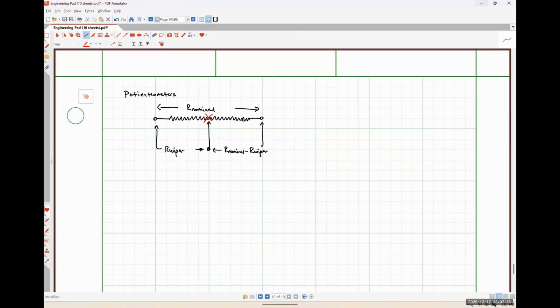Oh, actually, I guess one last thing. You can get potentiometers that have a linear taper, meaning that it's just a straight relationship. And then you can get ones with what are called an audio taper or a logarithmic taper. So audio taper and logarithmic taper are the same thing. They achieve that by literally just making the carbon trace get wider as you go across the wiper. So if you have a 500K pot with a linear taper, you'd be at 250 kilo ohms if you were exactly in the middle. With a logarithmic taper pot, you might be at like 100 ohms when you're in the middle, and then it will exponentially increase to the full value when you get closer to the far side of the wiper. But anyway.